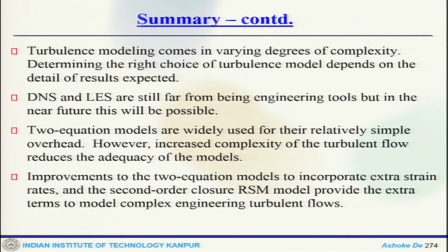So this is a summary of modeling at various degrees of complexity, where RANS based models are often used for engineering problems, and if you want to capture everything, then go for DNS or RSM kind of models. That covers pretty much what kind of modeling is required for engineering problems or small scale problems, and the issues.